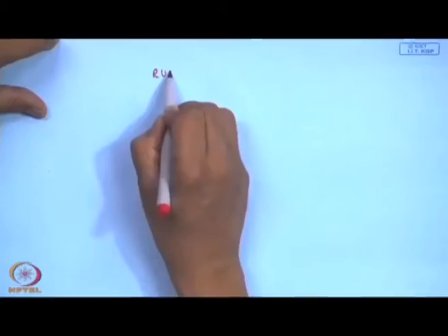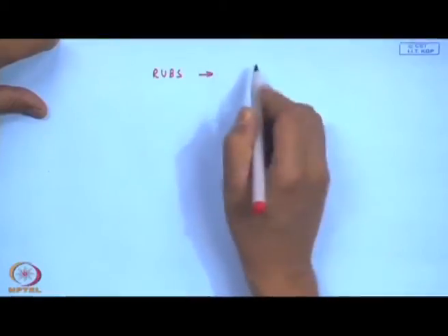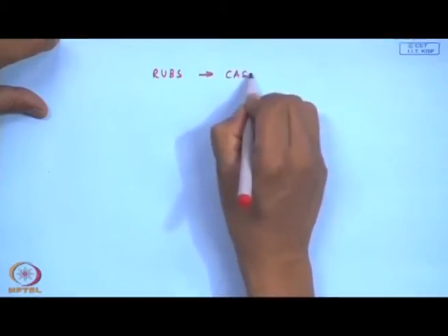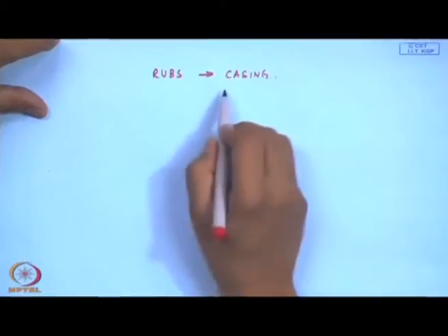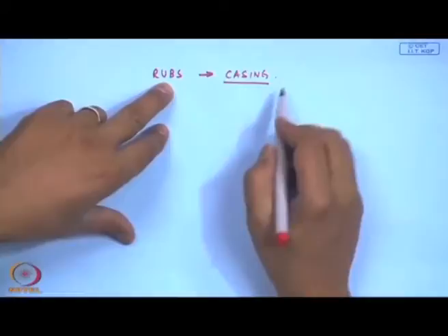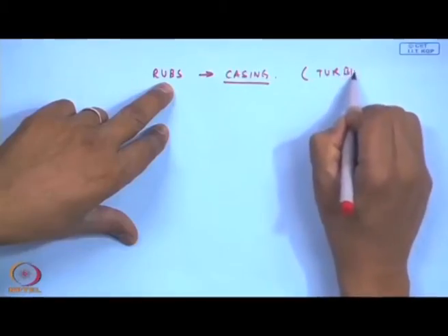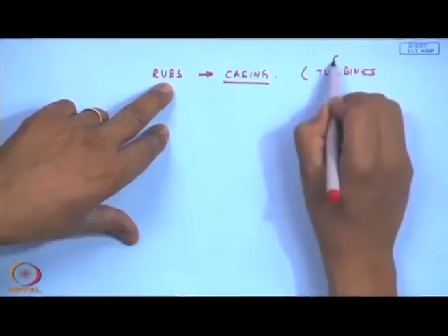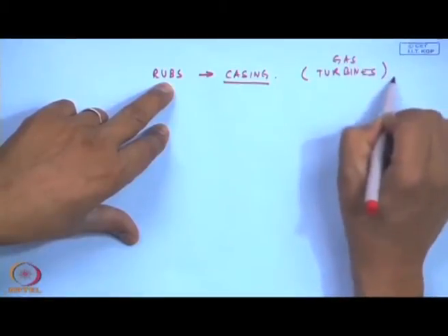And associated with these impellers getting defected, there will be load on the bearings and then misalignment. So, eventually they will rub on the casing. This rub, I told you in the case of the pumps, is also severe in the case of turbines, particularly gas turbines. Okay.